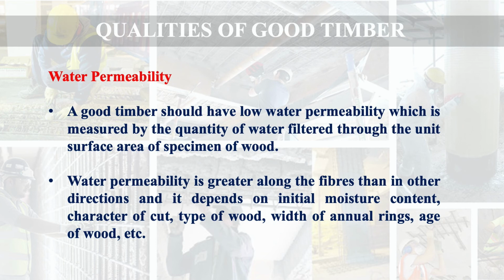Water permeability is greater along the fibers than in transverse direction or other direction, and it depends on initial moisture content, character of cut, type of wood, width of annual rings and age of wood. So these are the factors which govern the permeability of timber.